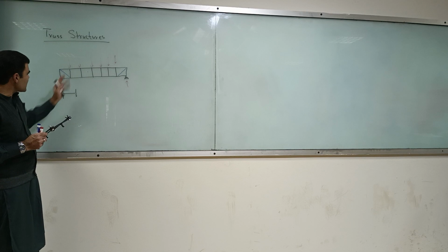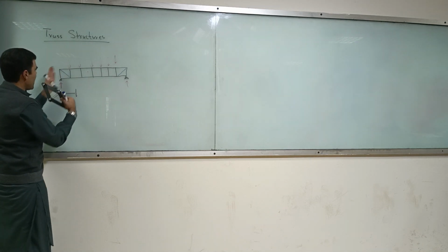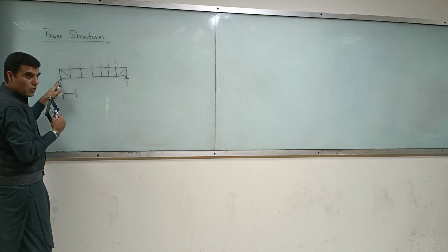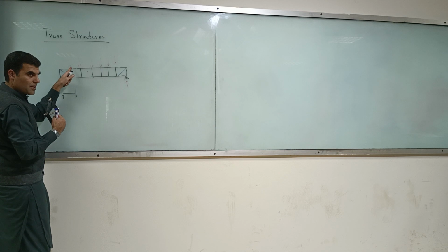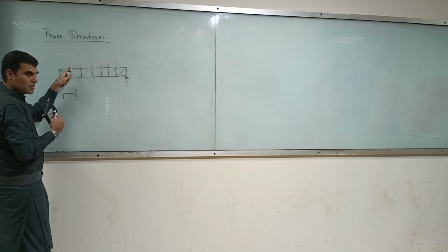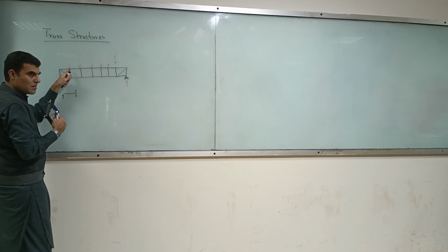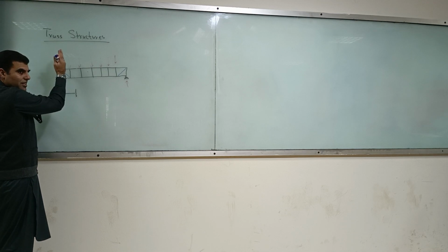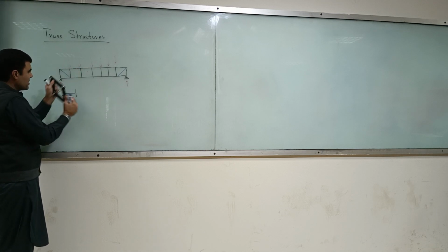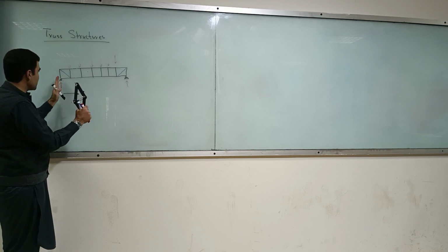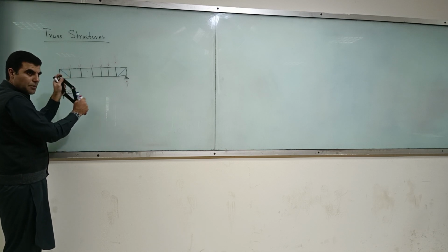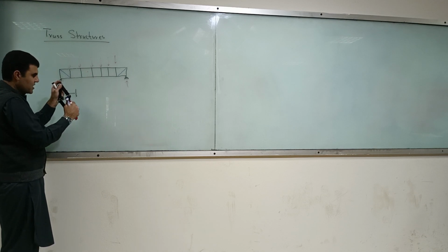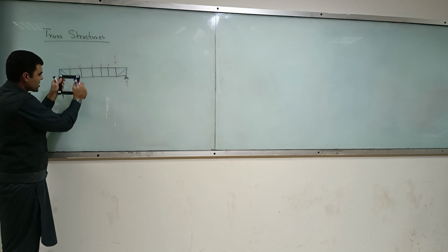Okay? So on this side, I have force in this direction. On this side, I have this force minus this one. So lesser magnitude, but you will have it in the opposite direction. You have got net force in this direction, in this link. Over here, you have got net force, this minus this, upwards. So summation of Fy must be equal to 0. You must have another force in the downward direction.